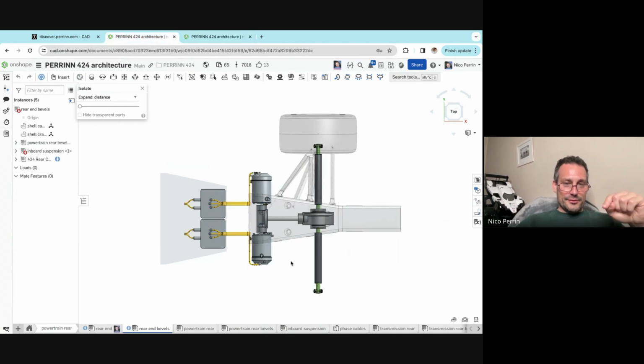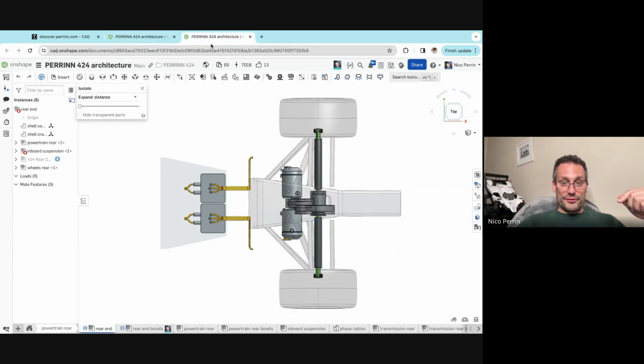The reason I had designed this at the beginning was because I thought about the center of gravity, we wanted more mass to the front. Being a four-wheel drive, I was worried that we were going to be too heavy at the back, especially because the battery is at the back. So I moved the motors away from the rear axle using this gearbox. But then when we did more dynamics, driving simulation, we realized, no, we want the weight distribution at 47, not 48.5. And actually, I'm happy with that. So that's why I've pushed the motors back nearer to the rear axle. But that allows us to build a gearbox with straight gears, which is actually more efficient.